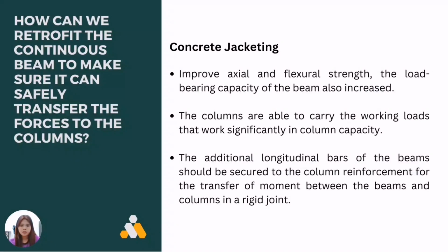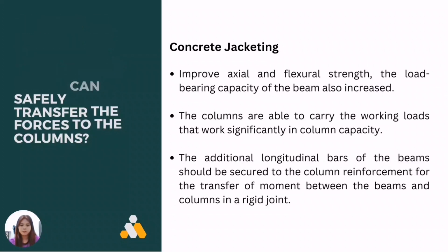After the jacketing, the columns are able to carry the working loads, which works significantly in column capacity, especially when there is an increase in moment capacity. In addition, the additional longitudinal bars of the beams should be secured to the column's reinforcement for the transfer of moment between the beams and column in a rigid joint.